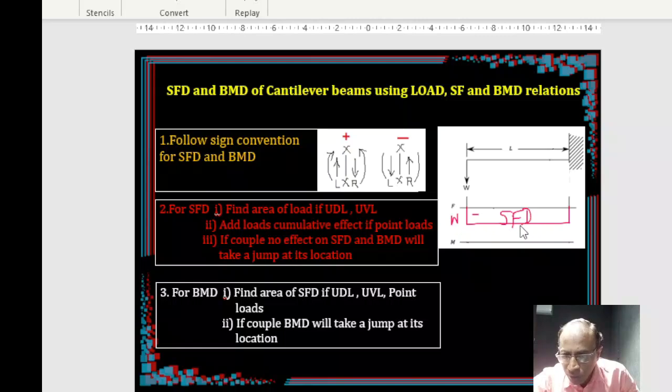Similarly, when you are drawing the bending moment diagram for this concentrated load, I told you, for this you can simply use the area of the shear force diagram. So at the location, at the point 1, say here, okay, 0, because there is no area, so this is 0. And if you want the ordinate at somewhere here, you can even find out at the middle also, say point 2. Like earlier, we can also take 3 points here.